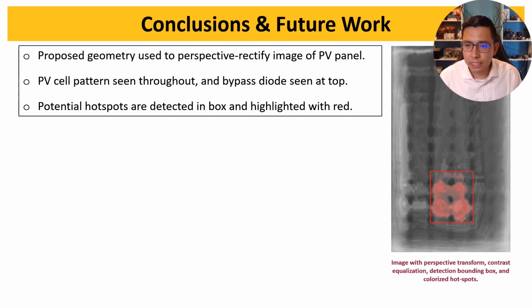We would then take these segmented imagery, do a perspective transformation to return that to the original aspect ratio. In this image at right, you can see that a bounding box has been drawn around areas which show higher than average heat characteristic. But hidden behind my speaking face here, there is a bypass diode, another hot electronics, which we would not like to detect. And so it's necessary to detect only some hot things and disregard others associated with these photovoltaic panels.